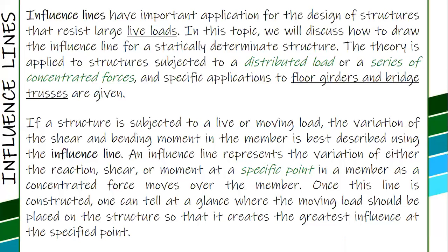So, the assumption is the load will move from left to right. And every time we move the unit load, the value of the reaction, shear, or moment changes. So, using the influence line, you can see the change in its value every time you move the unit load.